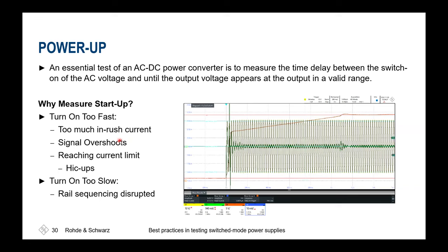And typically you'll need not only one or two channels. You also need several of these different signals to correlate the system behavior. Then you're seeing what voltage is coming here and what current is consumed at the end, and whether these still match the requirements that I've been given in the datasheet upfront.